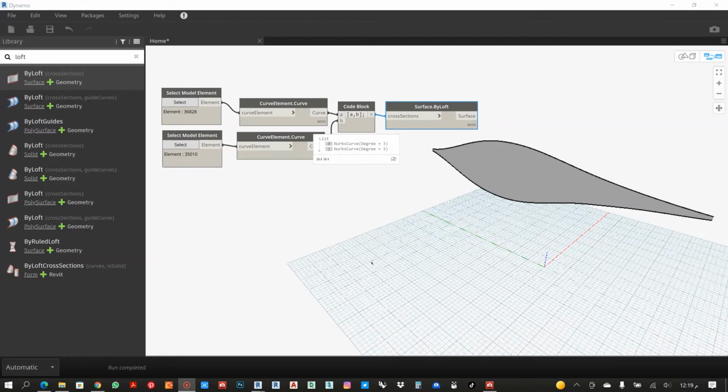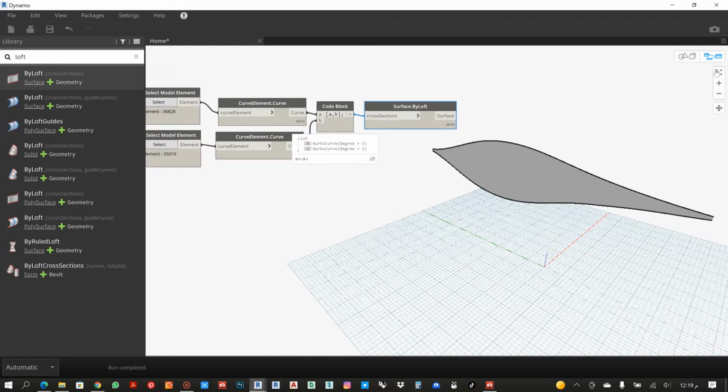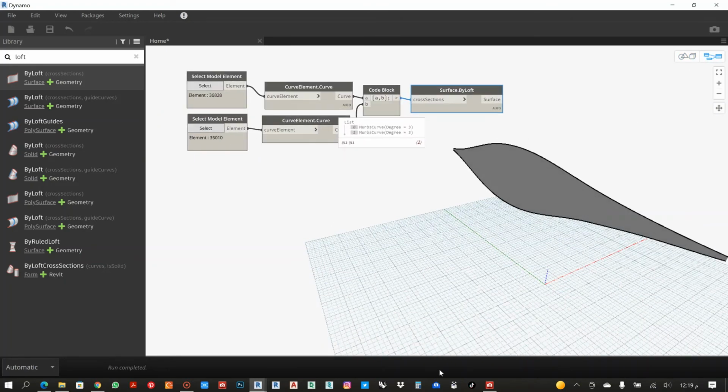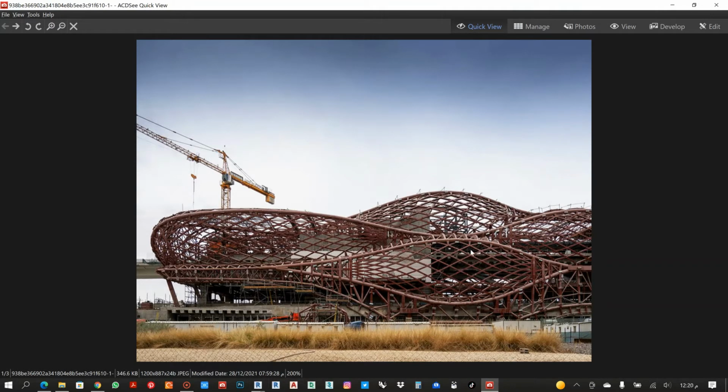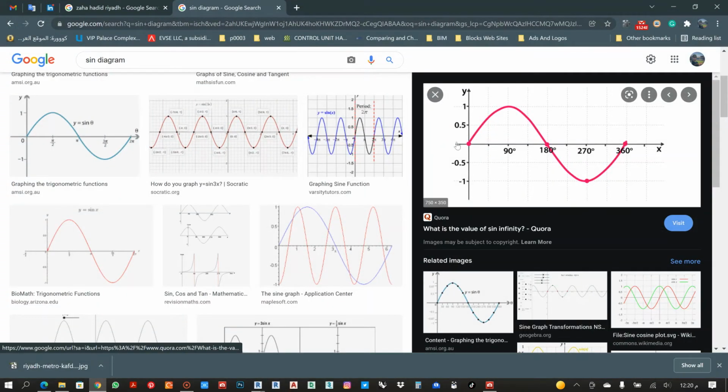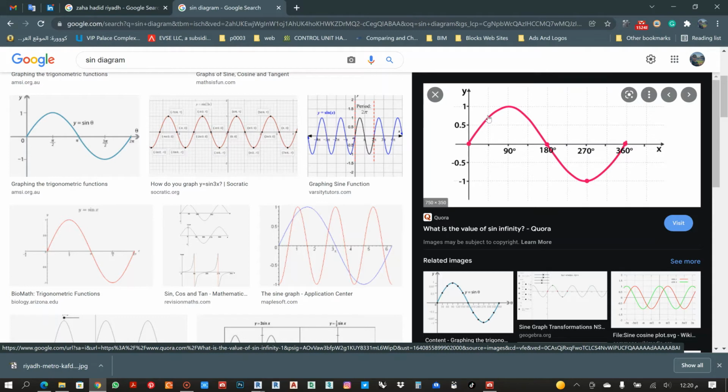And now regarding the shape we have, you can see here we have it as a flat surface, but regarding the design and concept of the elevation, the surface is already curved, not flat. So to do this on the surface, we need first to make an equation for sine regarding the degrees, and make a point distribution on the surface. And by the sine equation, if we see here, the sine equation from 0 to 100 can give you the curve that I needed. So I will place the points according to these angles to give me this curved surface.